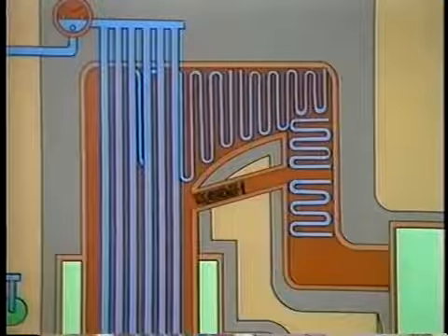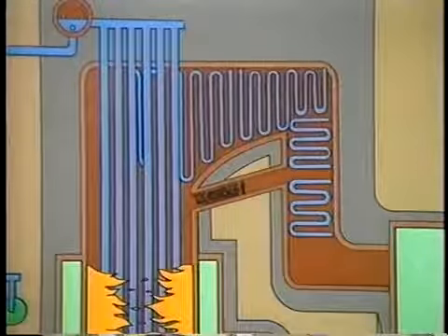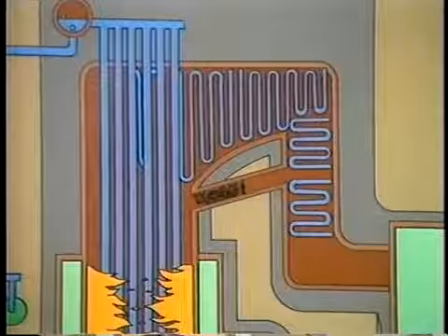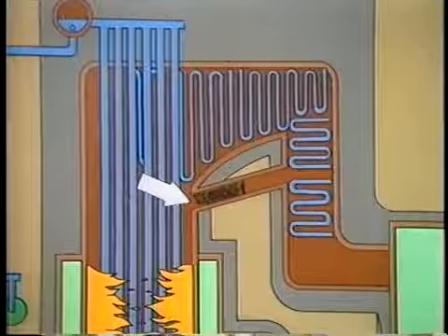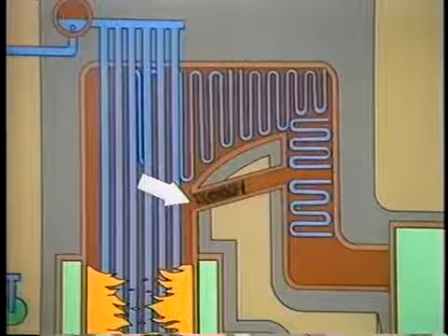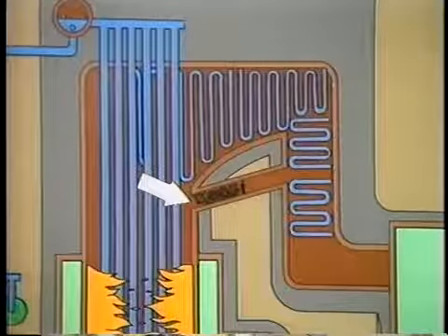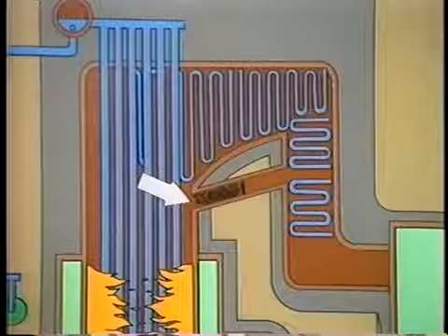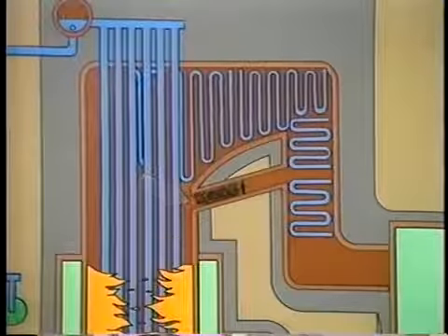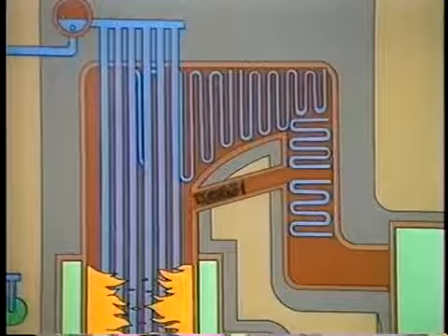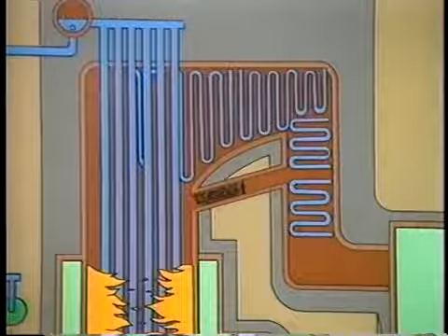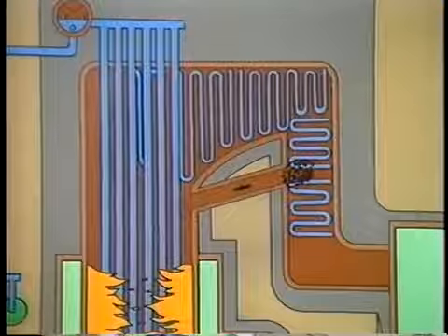When purging was complete, the operator followed the proper procedures for reestablishing the boiler flame. But remember, combustibles remained in this dead spot in the ductwork. The boiler continues operating for some time with nothing unusual happening. However, let's suppose further that the operator needs to adjust superheater outlet temperature and opens the bypass damper.